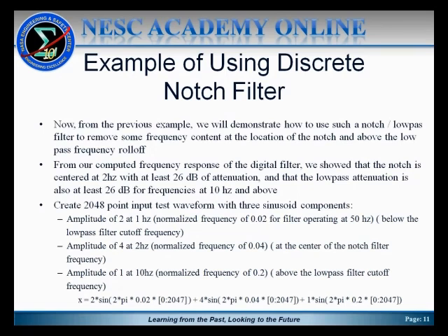Now you want to say, okay, I'll show an example. How would you use this to do something? The reason you define a notch low-pass filter is to try to filter out some undesirable characteristics for, say, a sensor, where you want to notch out some noise that's present, or your flight controller might be very sensitive to signals at certain frequencies that you want to notch out. So I'll show how you would actually implement such a filter.